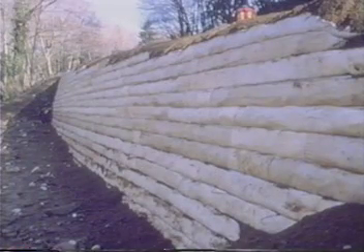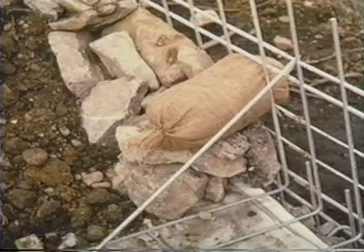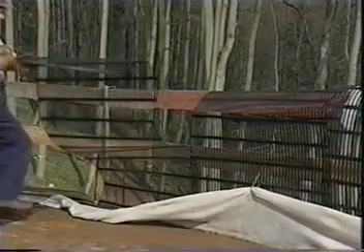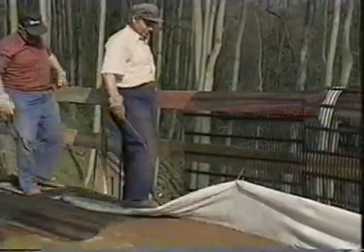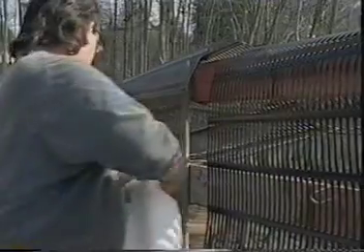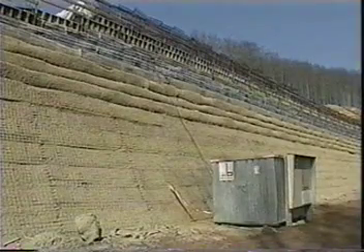Soft facings can be wrapped or caged. Geotextiles and geogrids are soft facings. Being compressible and flexible, they serve to reduce shear loads in the fill reinforcement, which might otherwise be induced by differential settlement between facing and reinforcement.